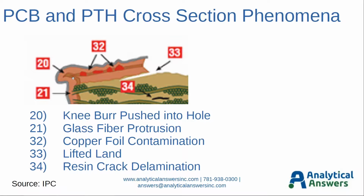So this was probably due to poor drilling techniques that were used. Either feeds and speeds were wrong in the hole drilling, or there were too many hits on the particular drill, and we got this particular burr that occurred because of that, and it's actually protruding out into the plating here, into the hole. And we're going to see one of those a little bit later.